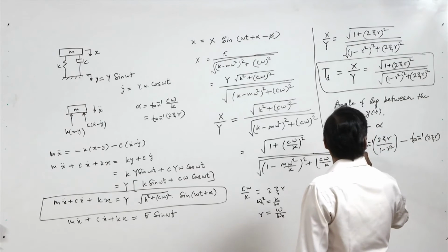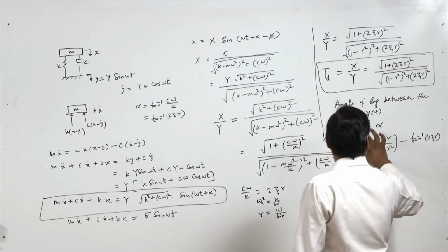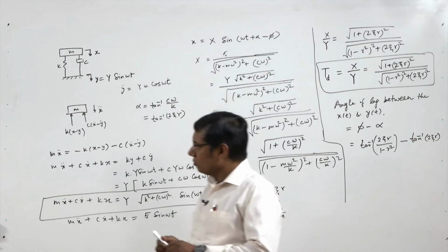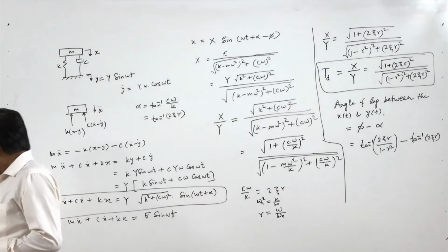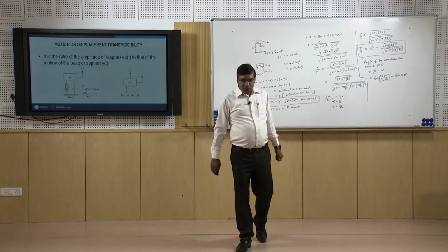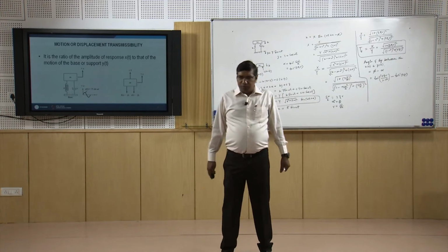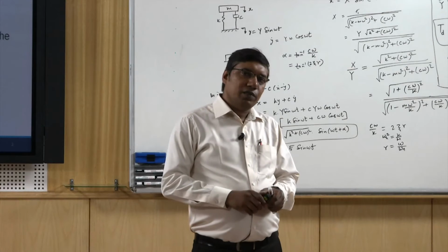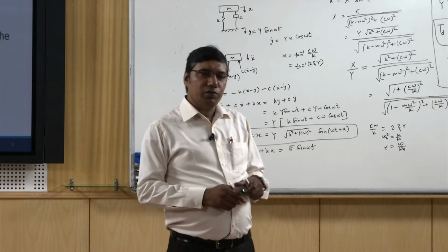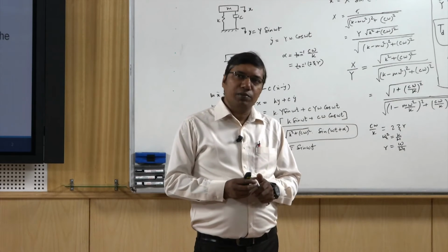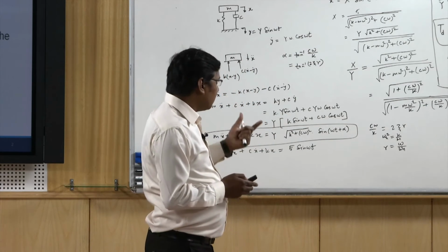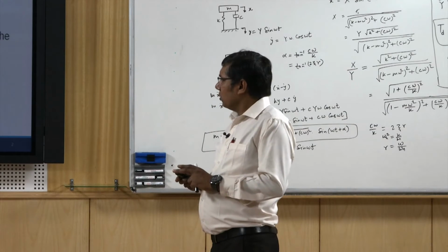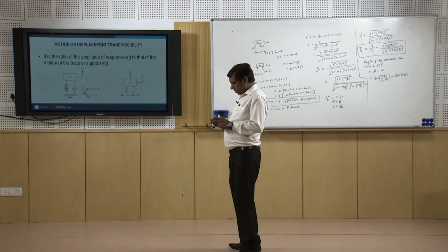So this is the angle of lag between the two motions. We see that the angle of lag is similar to what we obtained in the force transmissibility, that is, how much the transmitted force will lag the impressed force. So it is the same, and there is some relation between these terms.